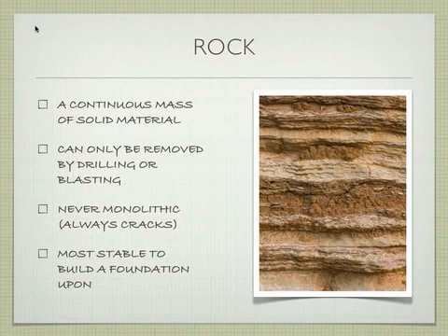Generally speaking, to confirm that you are actually dealing with rock, it can only be removed if you're going to blast it or drill it. If you can remove it with a backhoe, then it's a whole bunch of smaller rocks, which is not quite what we're talking about here. This is solid rock. So you need blasting, or you need to drill and fill it with epoxy, which cracks the rock. That sort of thing.